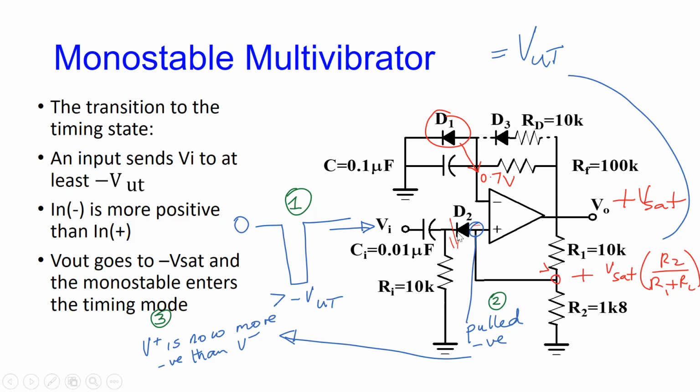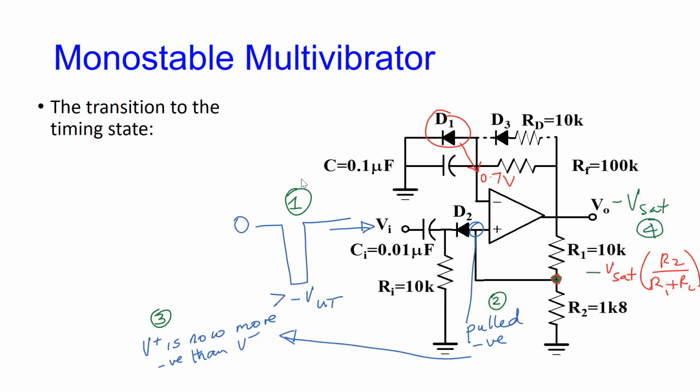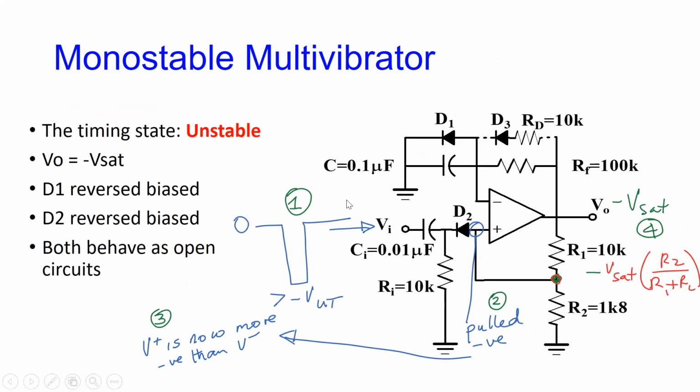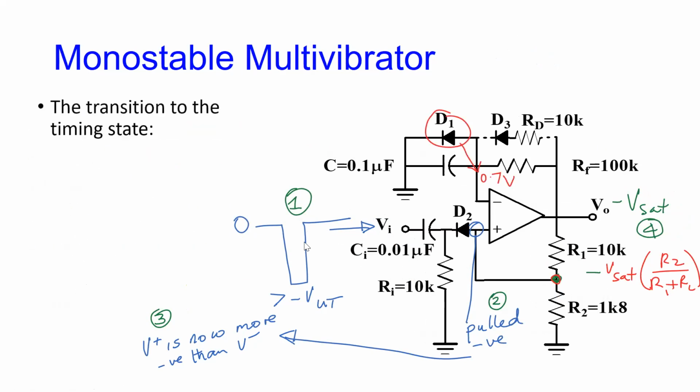Right, and it doesn't need to do it for too long. That's what this little network is about. It's really to give you the sort of sharp pulse, so you don't have to physically hold this too long. Once you send it low, the RC network here takes this and gives you this.